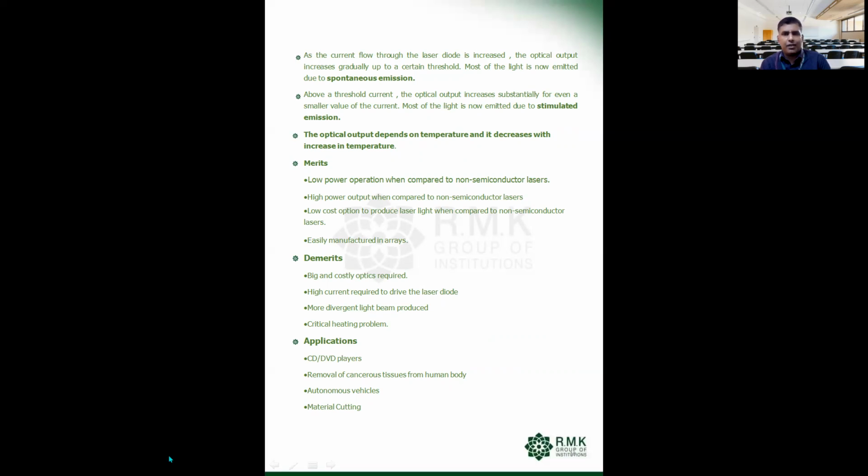And in this session we have covered LED as well as laser diode, and of course these are all basic extensions of the PN junction diode. So once we are thorough with the PN junction diode, we will be able to understand. All these diodes operate in the forward bias condition, and the only difference is the way in which the energy is made to focus. In a PN junction diode, we don't have any reflective coating. In an LED, we use a compound material, but still there is not much of a reflective coating. But in the case of a laser diode, we do have a partial and a fully reflective coating material, which makes the diode emit a very, very focused beam as a laser beam.